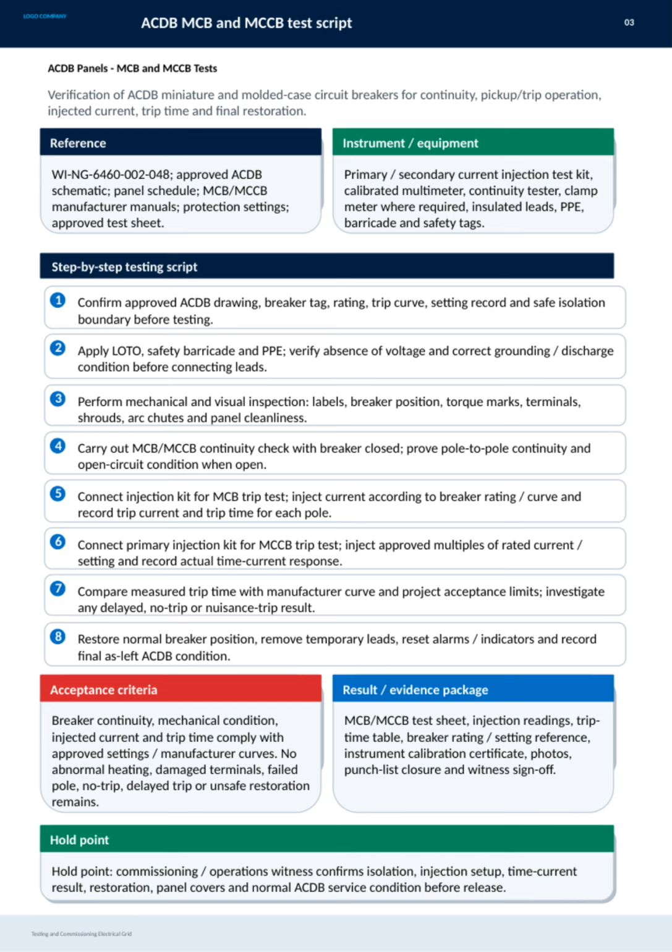As evidence, we compile MCB/MCCB test sheets, injection readings, trip time tables, reference documents, instrument calibration certificates, photos, punch list closures, and witness sign-offs. Importantly, before releasing the panel to normal service, a commissioning or operations witness must confirm isolation, injection setup, test results, restoration, panel covers, and overall ACDB condition at the hold point. This ensures safety and reliability for the electrical grid operation.